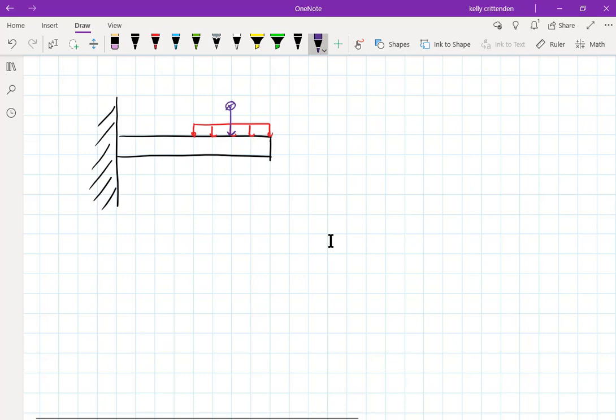That won't get you quite the same effect though, because if you lumped it with the point load where I show it, then that B section of the beam you would treat as linear, but it really has a distributed load across it, which is curving it. So that's not the best way to do that one, although if you just wanted a quick way to calculate it, that might be one way to do it.